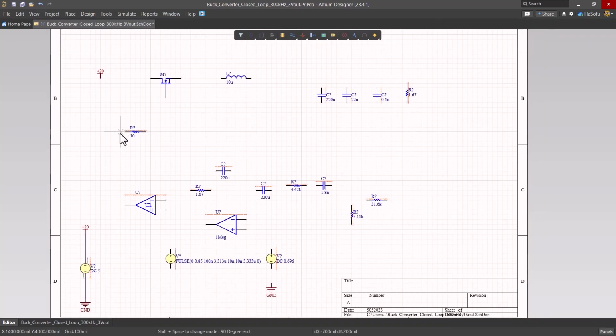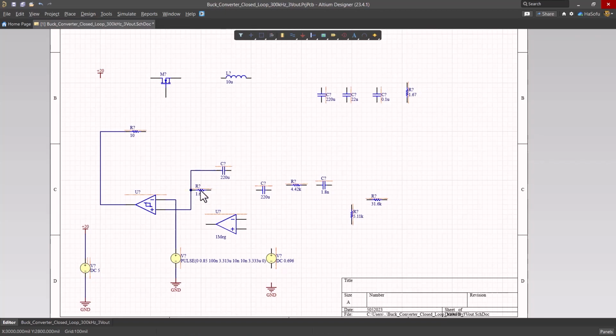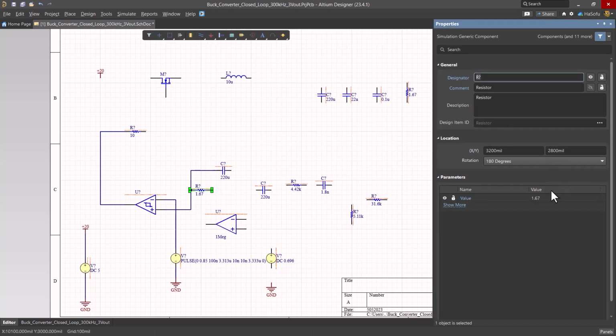So to wire up the circuit, we're going to start with Control W as a shortcut and then start making these connections. My negative terminal is going to go here to my sawtooth waveform. Copy this ground, place it here, make the wire connection. Then for the comparator, this would go into my compensator circuit. My capacitor here, resistance here. Oh, also this resistor, I didn't change or update this. I'm going to change this to 5.23 kilo ohms.